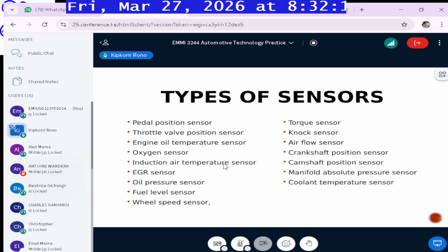So that intercooler simply cools the air or reduces the temperature of the intake gases so that it does not cause problems, say, to do with auto-ignition, because auto-ignition causes issues like knock. Okay.